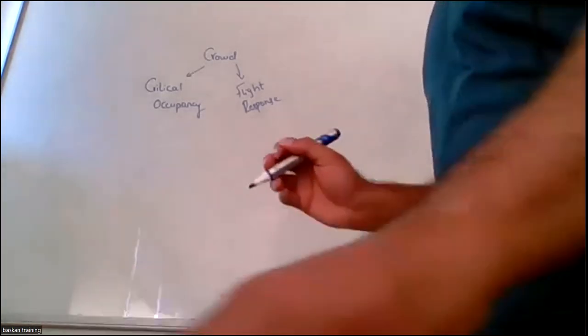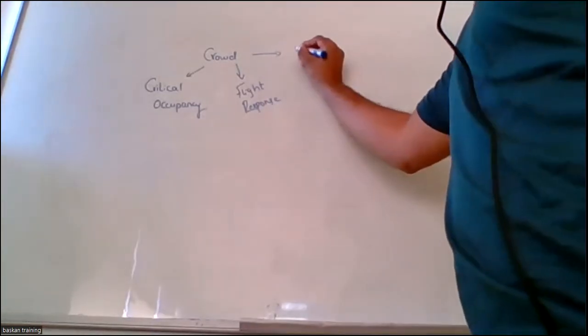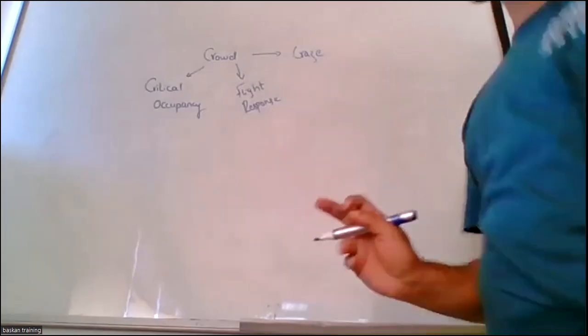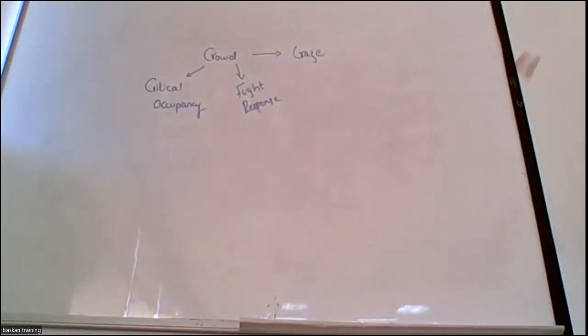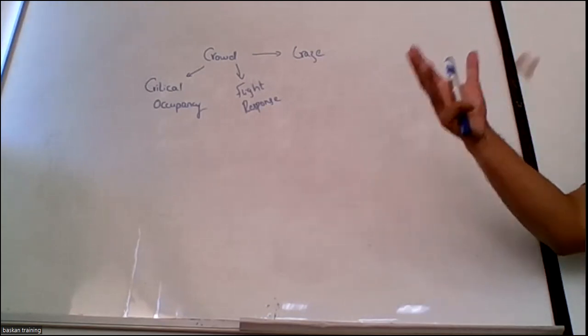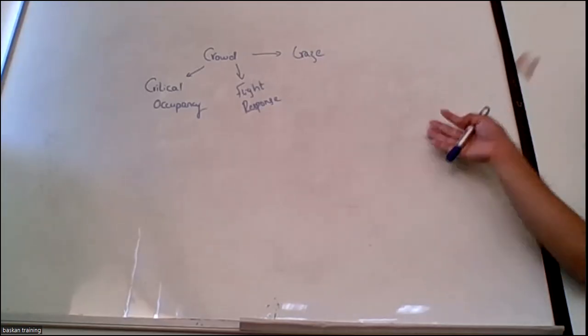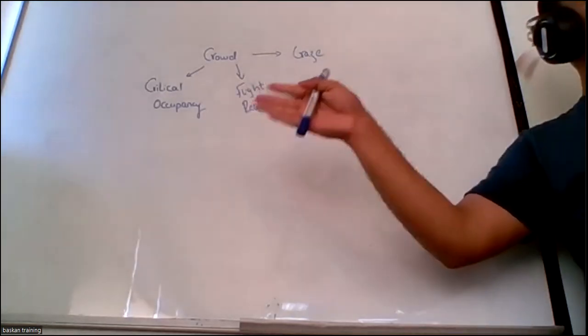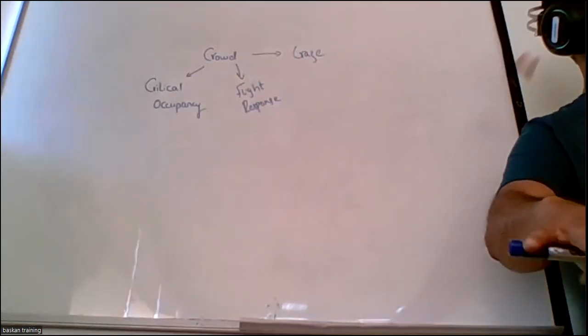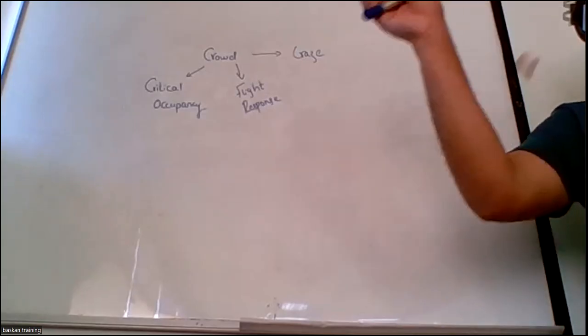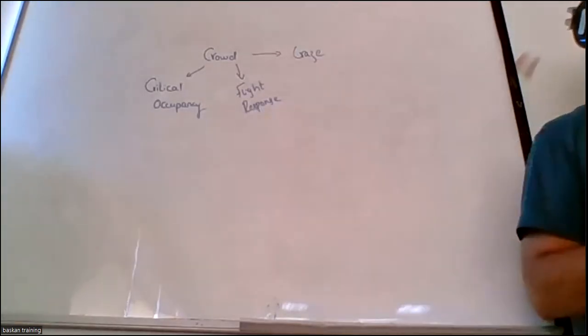The third occupancy factor is craze, where a hazardous crowd situation can occur. People tend to move on or push towards the railing. For example, if any famous celebrity is crossing by and there are barriers, everyone will try to move closer to him, right? So the force will be exerted directly on the barrier itself, and in case of a collapse of the barrier, everyone will fall down. There will be injuries or even deaths.